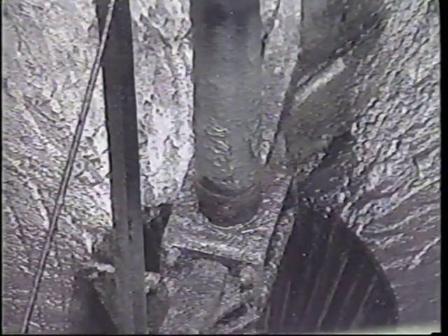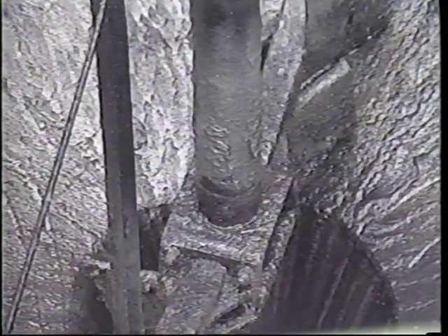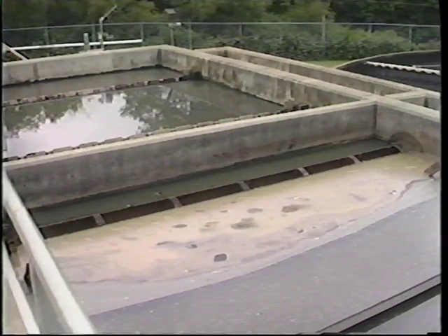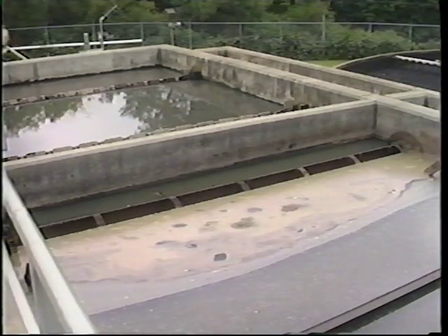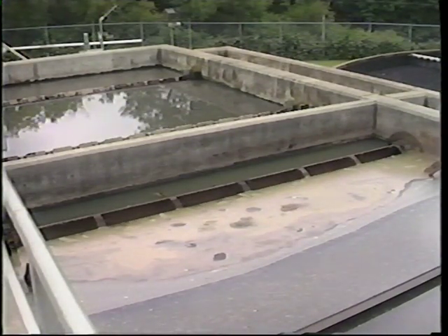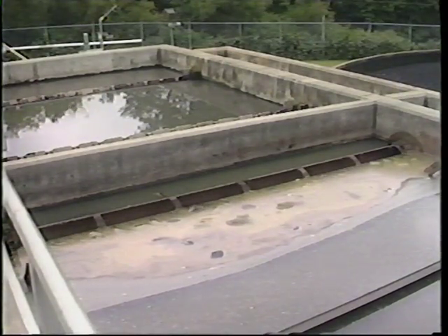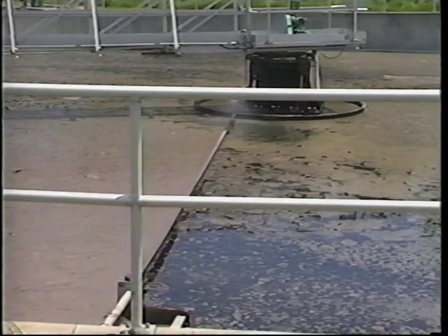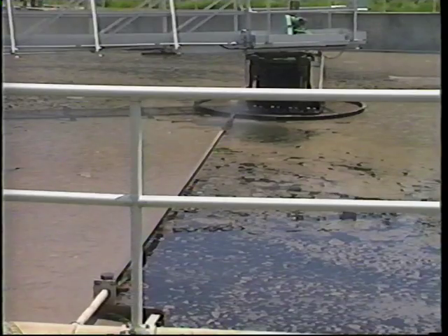Biosolids from primary clarifiers may also exhibit anaerobic or septic conditions as opposed to aerobic secondary biosolids. The floatable solids in a primary clarifier consist of grease, oil, hygiene products, and other materials that will float. Floatable solids found in a secondary clarifier are usually oxidized organic matter from the preceding biological treatment stage.